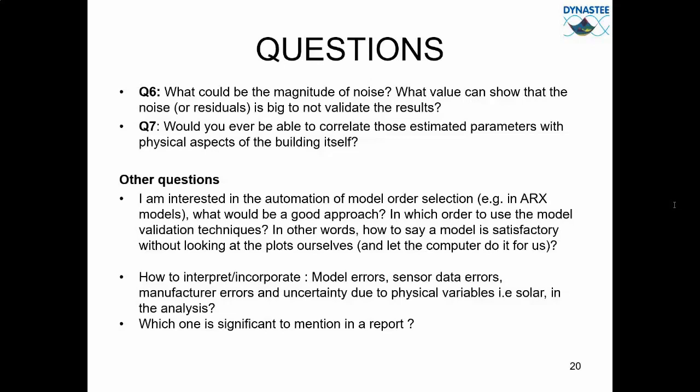So start with a simple model and add more lags until you obtain white noise. That's a simple and robust procedure, which should be quite simple to automate, and thus a simple automatable way to select the ARX models.